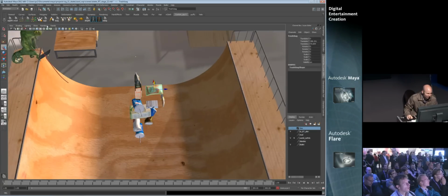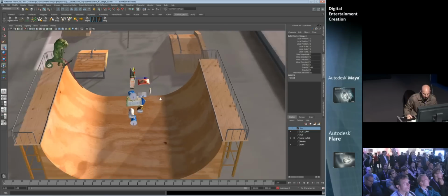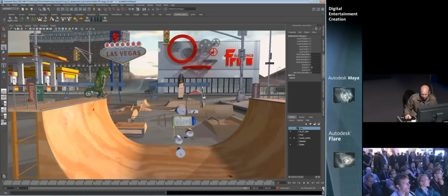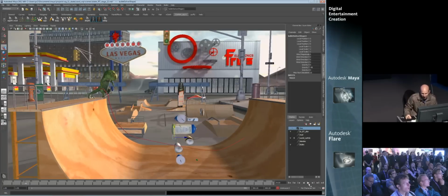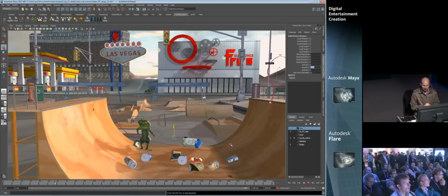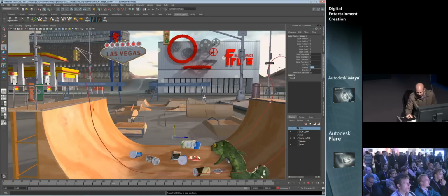Let's go ahead and create this into a cloth object. We'll add some attributes on that guy. We'll go ahead and change the parameters. Actually, we'll play it back once wrong. So if we play this back, let's make sure we're in our perspective view so our camera's not moving. The geometry is not going to drop very fast, so I want to modify the world in which this lives. We're just going to put that up to minus 980. There we go. So now they'll drop realistically. And just like that, we now have a really cool dynamic solve happening, objects coming down, soft bodies interacting with rigid bodies, constraints holding our dynamic tail together.